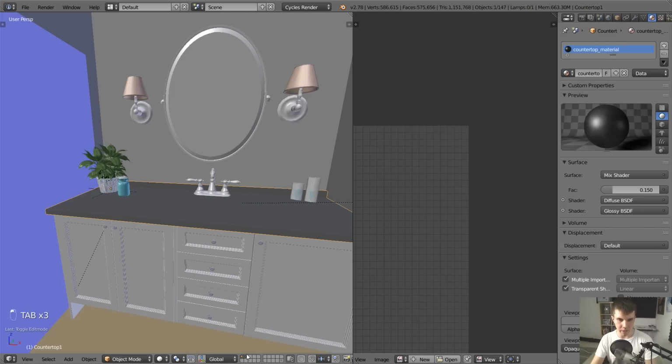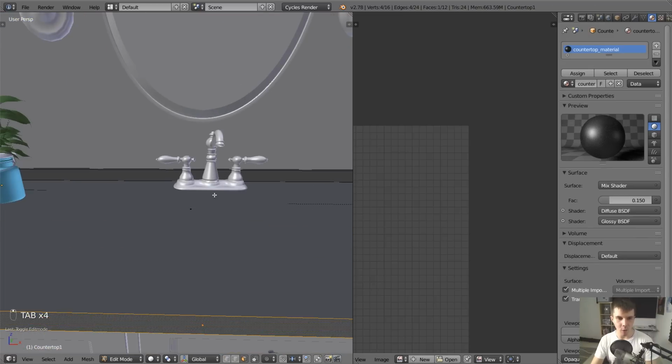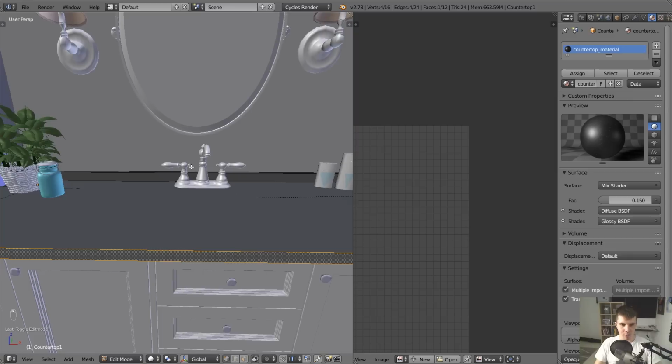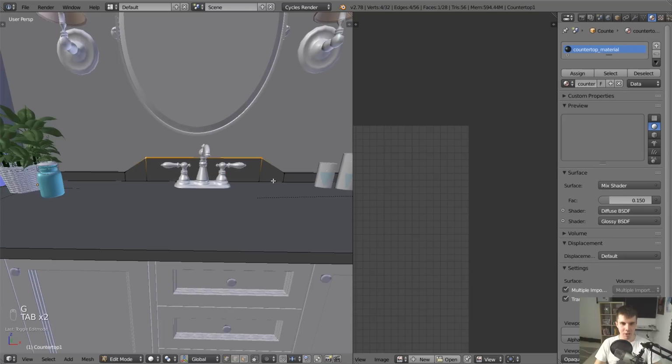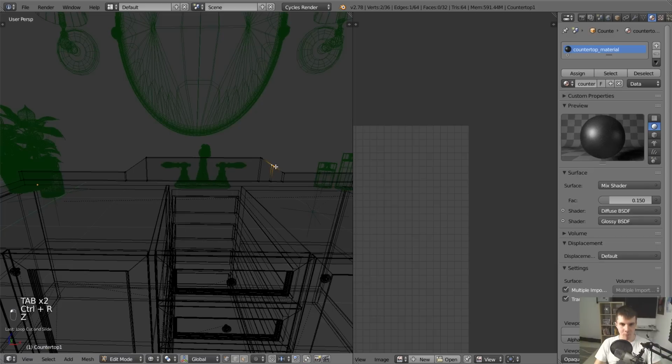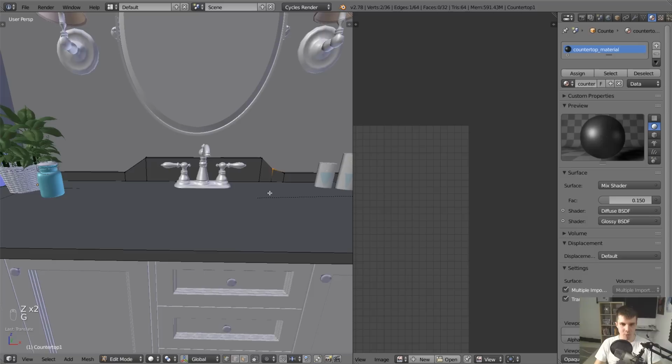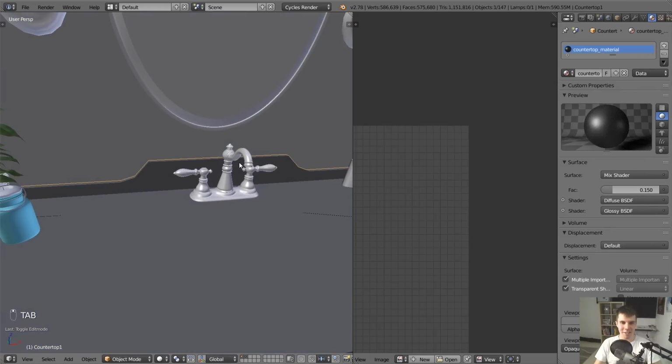And also, when we bring back our objects, I noticed looking on House that a lot of houses have this little splashback area, which is sort of raised. So I'll just add a loop cut here and a loop cut here. And then I'll just grab these two areas and I'll bring them up. Not too much, but a little bit. And then I'll move this down a little bit so it looks a little bit smoothed. I mean, if you really cared, you could properly smooth it with an actual curve. But right now, I'm just piecing it together.